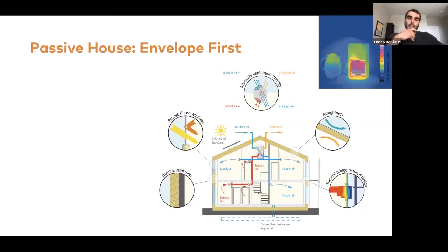And on the right-hand side at the top, that is an infrared image showing a coffee pot, just a regular glass coffee pot that is supplied with heat constantly in order to remain warm. And it is warm because you see purple in the infrared image. The fact that you can see purple means that coffee pot has a lot of heat losses. And the moment you unplug it, you start losing heat considerably. And that coffee pot does not remain warm for a long time.